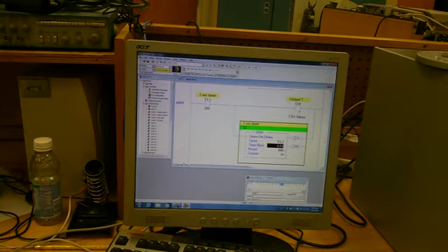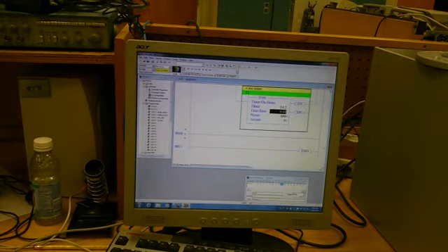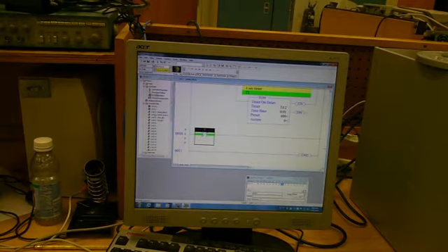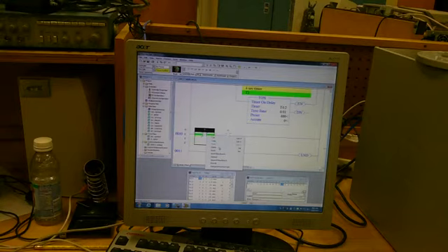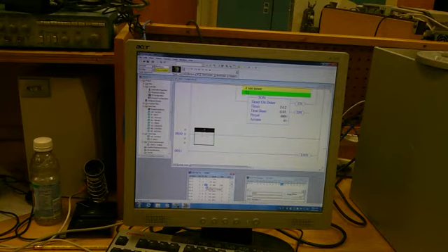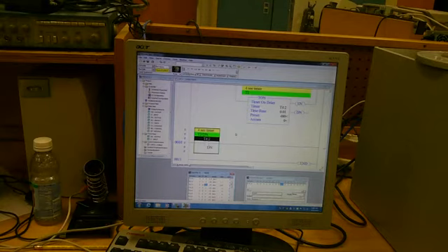All right, so where are we? That's the 4 second timer. Now we want one more. So we want this timer done bit. We'll bring in my timers again. And I got the wrong bit. We're doing a delete of that instruction. Okay, so we want the T4:3 done bit, so we'll grab that guy. No, we want the :2 done bit. All right, so now T4:2 is done.